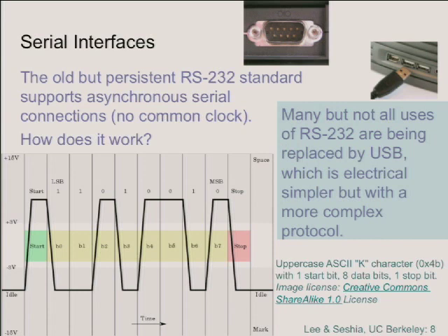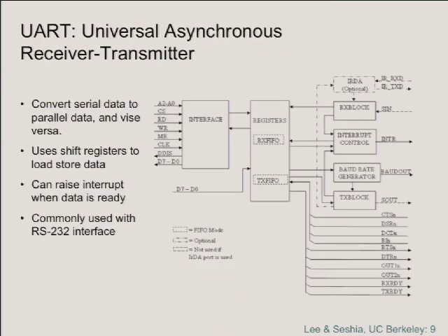So these things get latched into a register. So here's a picture of what the hardware looks like. Here this shows you can use serial links over infrared. The robots that we have, by the way, have an infrared receiver and transmitter, that little knob on the front, which can be used to receive and send serial data over infrared. So the robots can communicate with one another through this infrared link. People have used that in projects before.